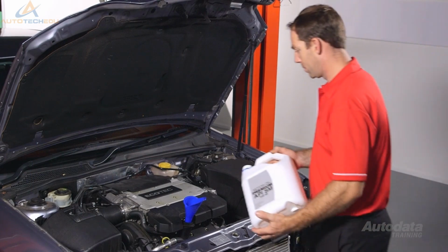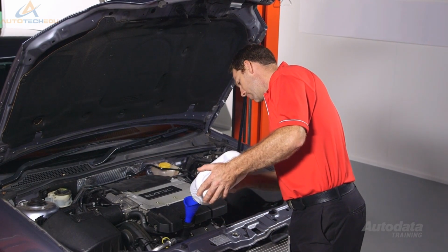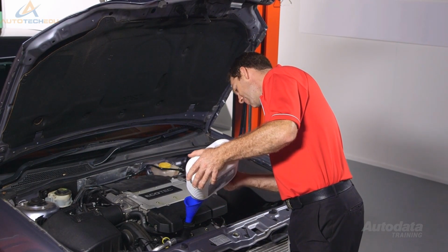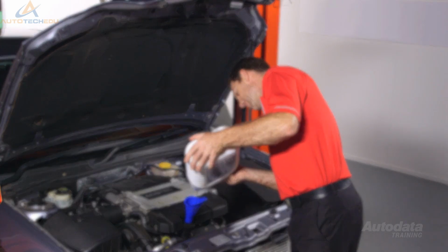It's also best practice to reset fuel trims after something as minor as an oil change. After any repair, long-term trims will eventually reset and adapt to new conditions. For customer satisfaction, always reset fuel trims as part of the repair. Understanding how fuel trims operate is relatively straightforward, but it's an essential part of any diagnostic process.